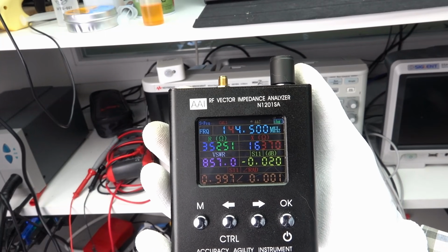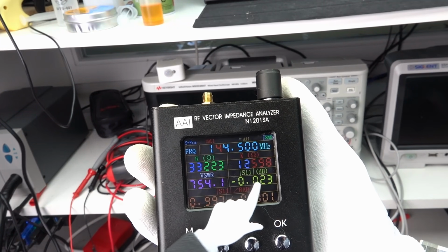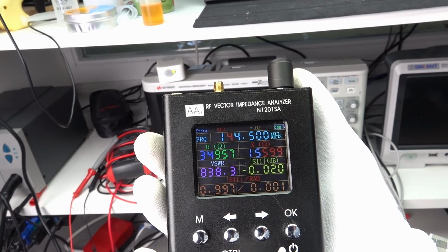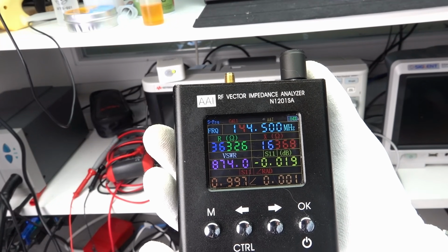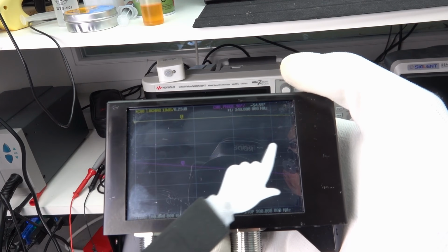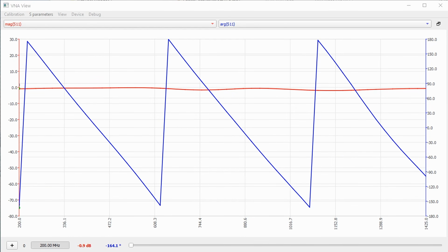For example, this VNA shows the impedance as well as the amplitude for a particular frequency. Nice. But most of the time we want to know the course of these values across a frequency range. This is why VNAs draw amplitude and phase curves across frequency ranges. On the NanoVNAs, the amplitude is called logarithmic magnitude or logmag, and the phase is called phase. The amplitude curve is more famous because it is used to determine the quality of a match.